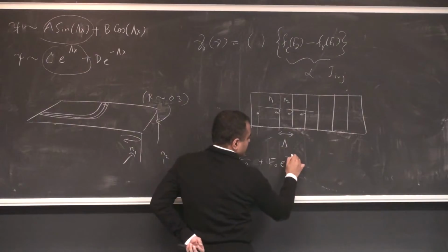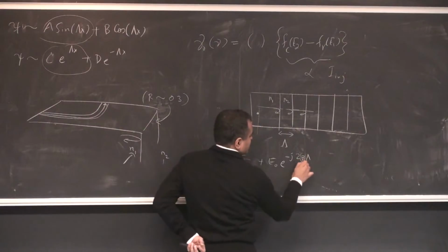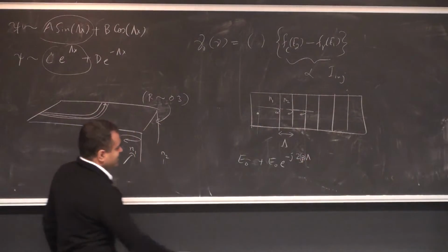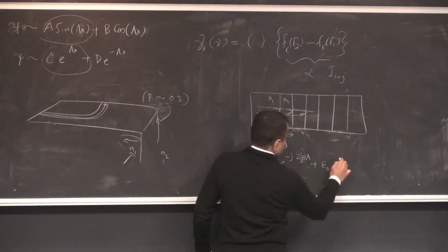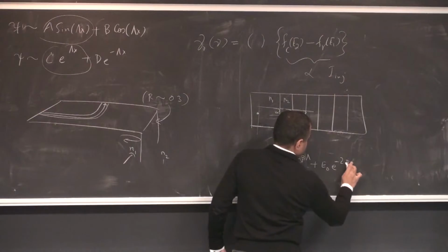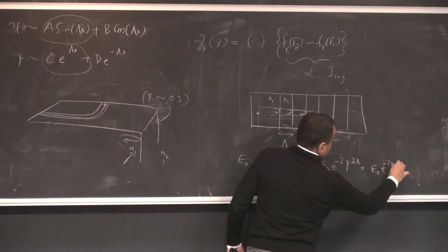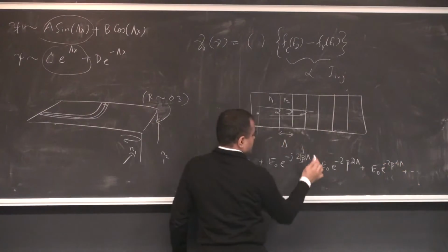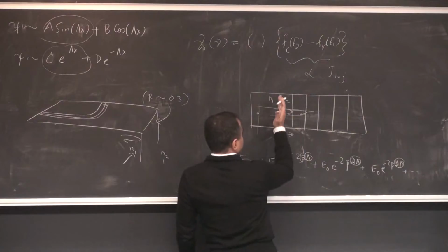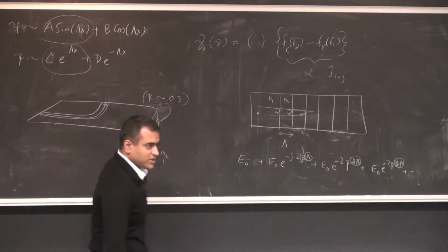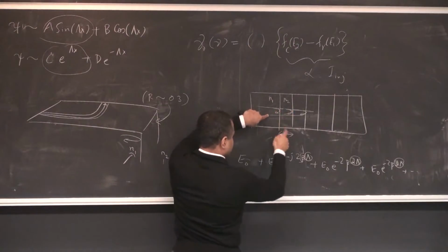You get one reflection with e to the minus j 2 beta, where beta is 2 pi by wavelength, and then two reflections from here, and so on, so you get a geometric series, with 0, then 1, 2, 3, 4, and so on. You get an electric field amplitude that looks like this. I think you know that if you reflect all of them and add them in phase, then you get a huge reflection, right?